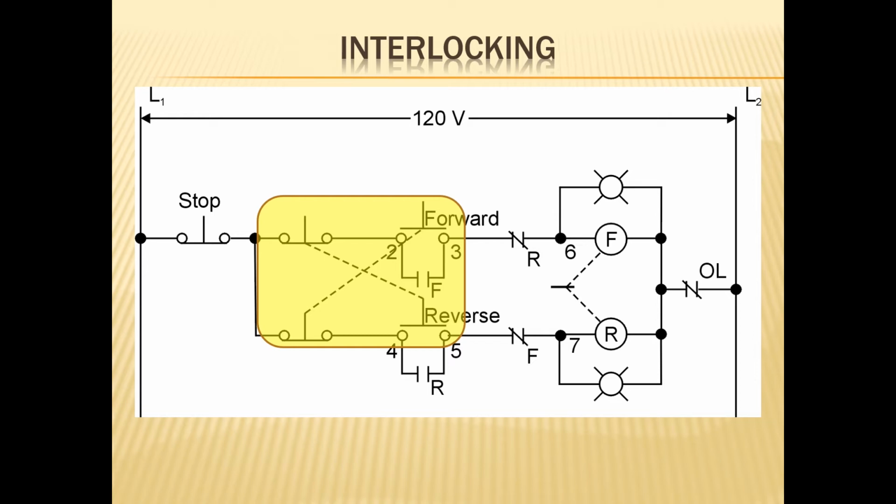For example, if I were to hit the stop button in the first line, since that is connected to the start button in the second line, this is my interlocking, where when I activate one button, both of those move at the same time. So my stop button in my forward circuit will also activate the start button in my reverse circuit at the exact same time.